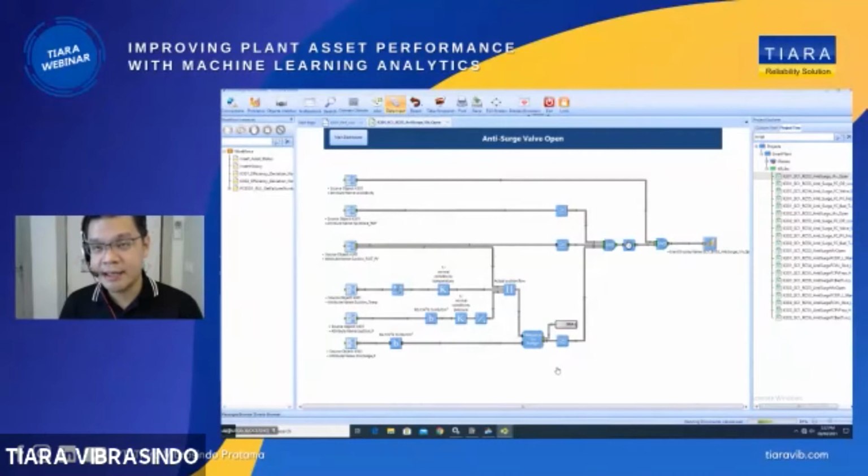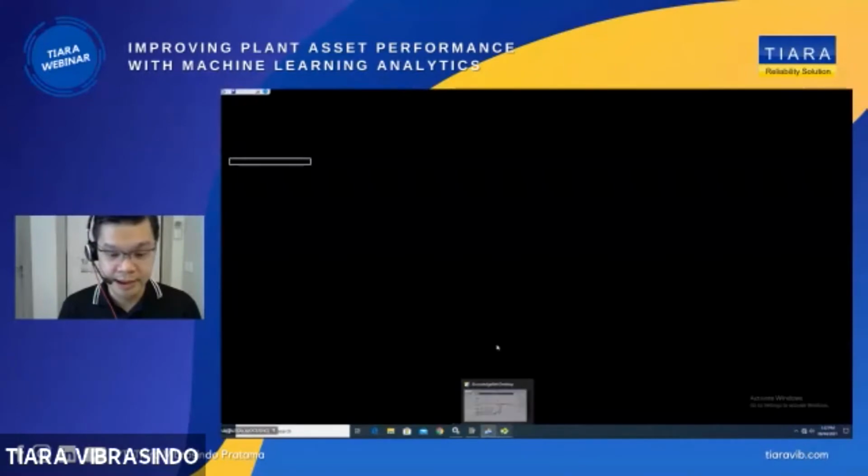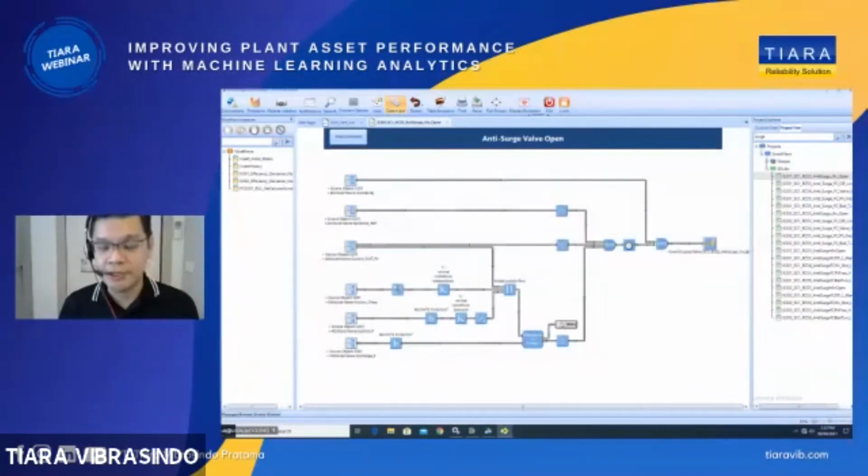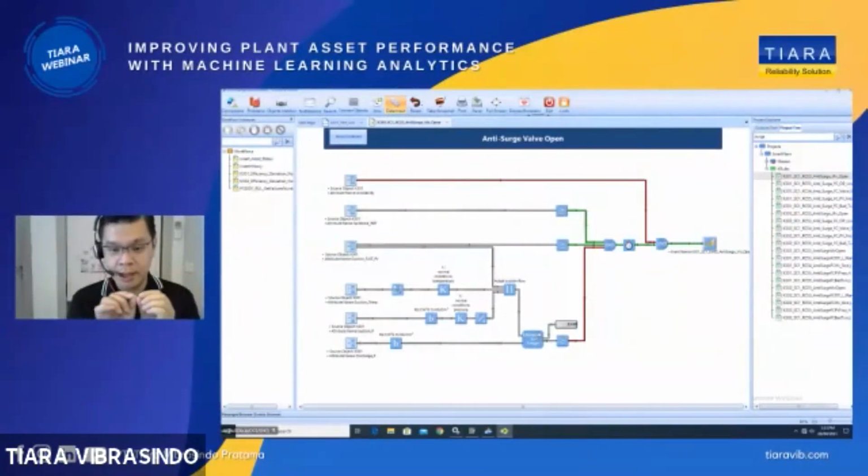You have a surge line chart, either in a PDF document or something like that. The modeling studio, later I will show you the modeling studio. This is actually the modeling studio. It's below here. Later I will show you. The modeling studio is able to convert your PDF document into a model here that can calculate where your current operating point is, the operating distance to the surge line.